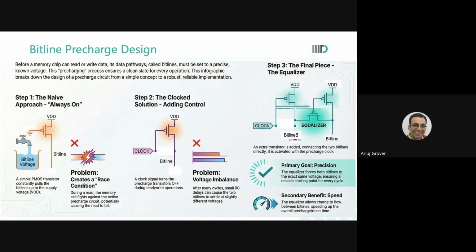Until now, you were looking at trade-offs between timings and area, or timings and power. But as an SRAM designer, you also look at trade-off between timing and timing. Interesting. Similarly, when we talk about address decoding, you will see there is a trade-off between setup and hold. Remind me to talk about it when we talk about setup times and address decoding. Is that okay? So the trade-off is between the cycle time and the read access time.